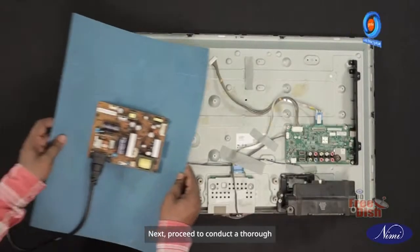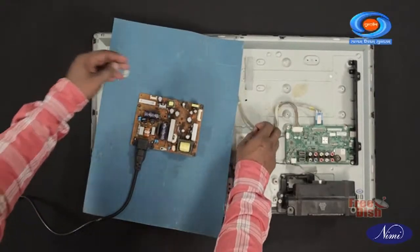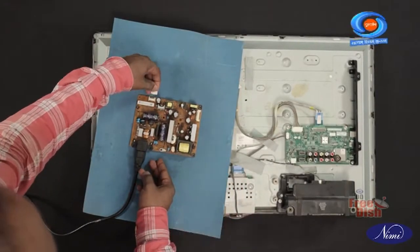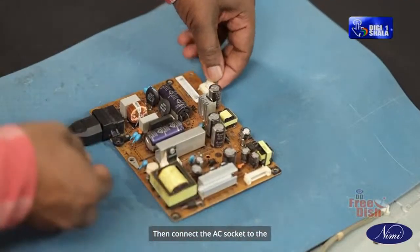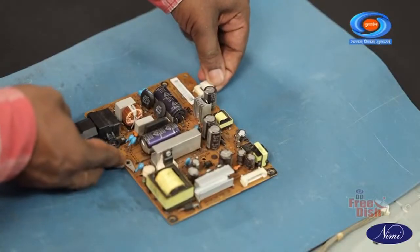Next, proceed to conduct a thorough inspection of the main board. Connect the main board and backlight cables to the power supply boards. Then connect the AC socket to the power supply and switch it on.